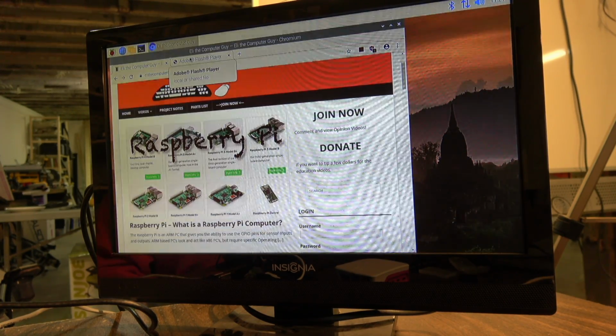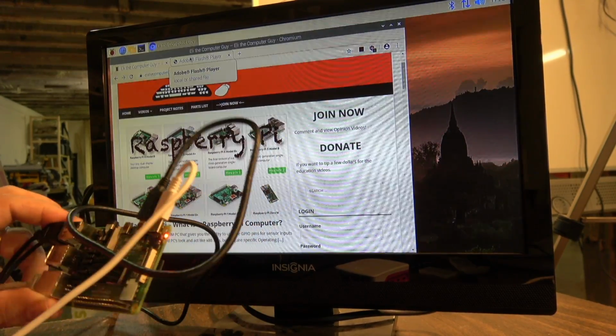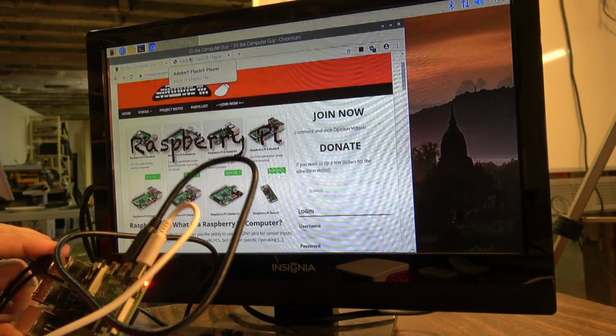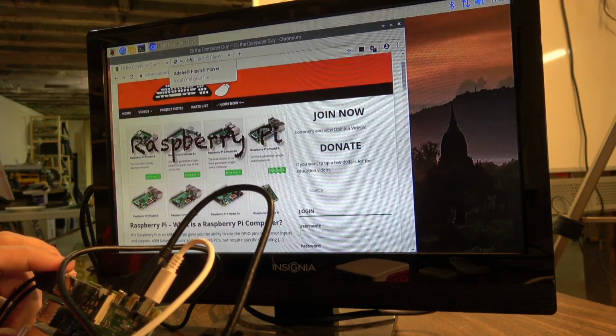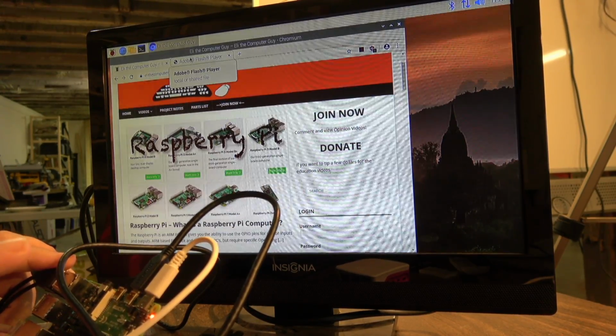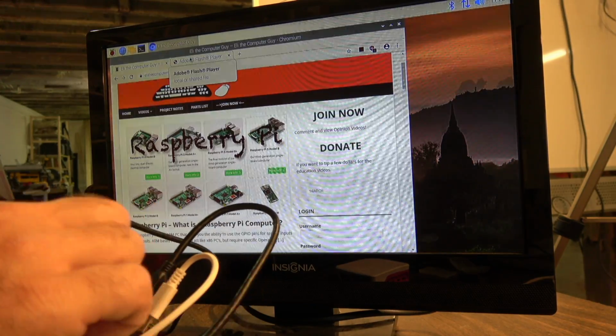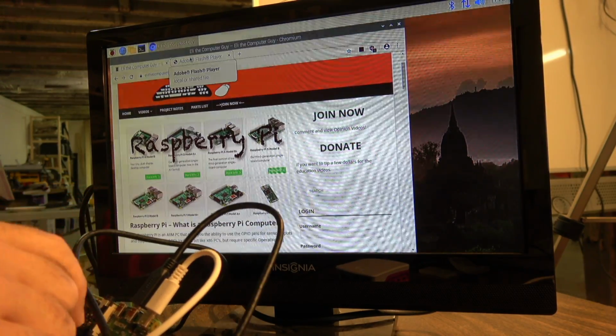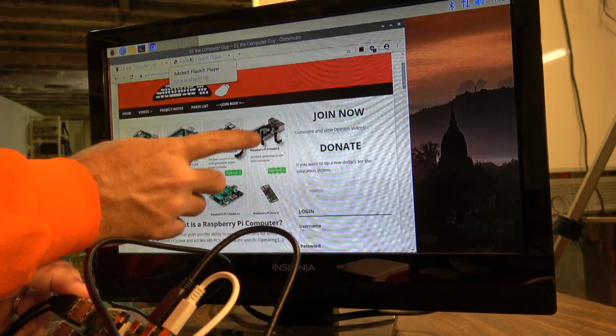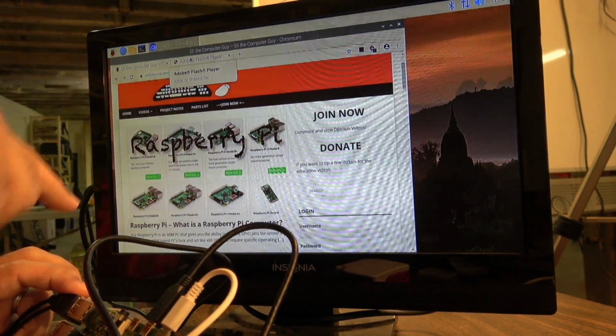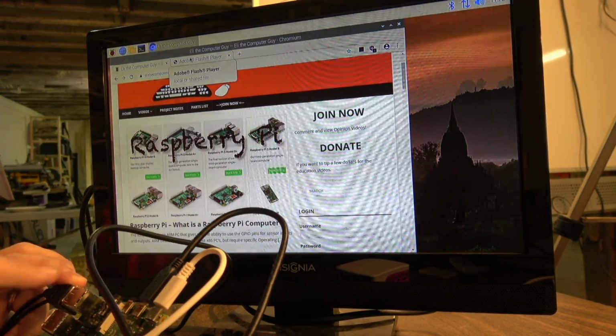Now, one of the things that I want to show you is a troubleshooting process. So whenever you're dealing with a computer, especially Raspberry Pi, you might have quirks, especially when it comes to the initial installation process. And so one of your questions has to be, if the computer doesn't seem to be booting for some reason, why? Is it a bad SD card? Is it possibly a bad HDMI cable? Does your television or your screen not like your Raspberry Pi for some reason? That can be an issue.